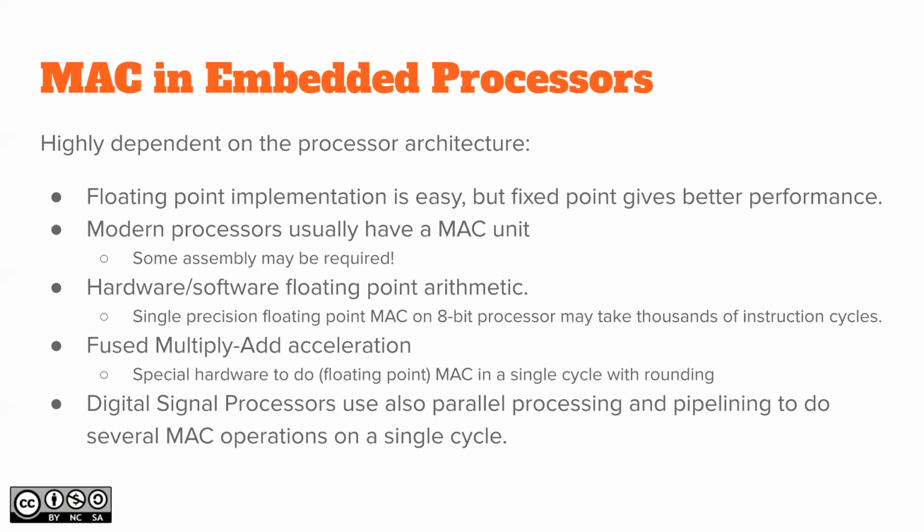But in general, there is a cost on floating point versus fixed point. Okay, that's a little bit too big a statement here. Fixed point gives better performance. No, it doesn't. If you have a highly tuned floating point arithmetic unit, then it actually does these calculations at least at the same speed as fixed point. But it takes about double the silicon space.